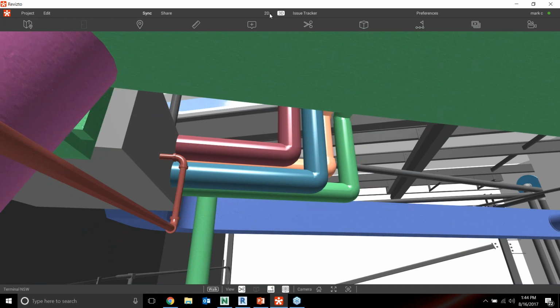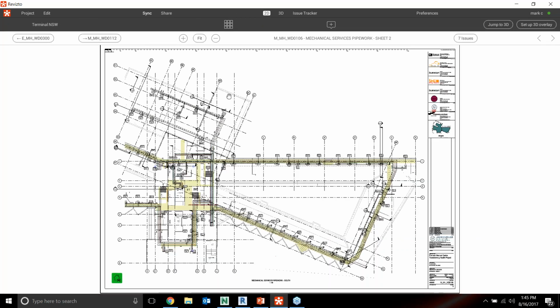So all these sheets that we bring into Revit are intelligent, and we can also do this with PDFs. So if you guys are getting PDFs posted to your project site, we can import those, and we can actually drag and overlay dumb PDFs where we lose all that intelligent BIM information when we convert that to the PDF, but we can assign those back coordinates inside of Revizto just by simply selecting the three different corners within the sheet and overlaying it on top of the model. Pretty simple to do and a great way to ingrain PDFs into the workflow.